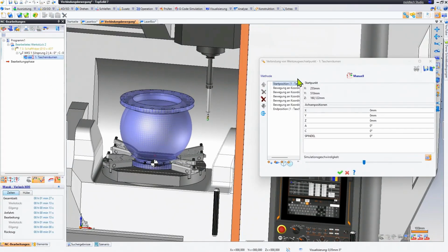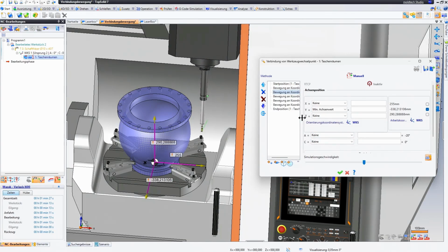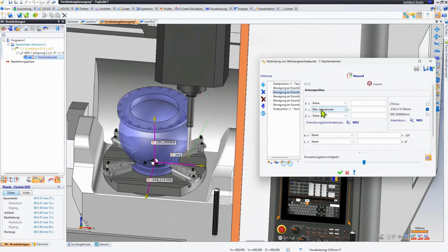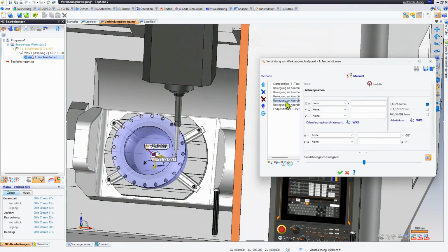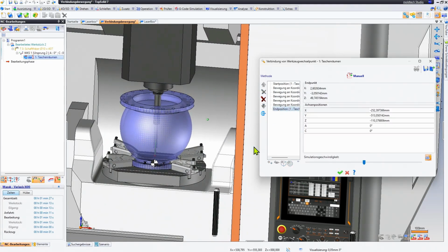That means you can clearly see the individual steps right here where I am now. First, you need to set the A-axis to -20 degrees and then move the tool carefully to the minimum axis value in the Y direction. Since you have the machine visible in the background, we can also specify both the minimum and maximum axis values there as well. For example, we can also say -1 millimeter, starting from this particular value. And I can always specify which is now the controlling coordinate system for the individual processes. Then it sets up and positions itself in the center. And then, so to speak, it performs the plunge movement and then moves to the final position.